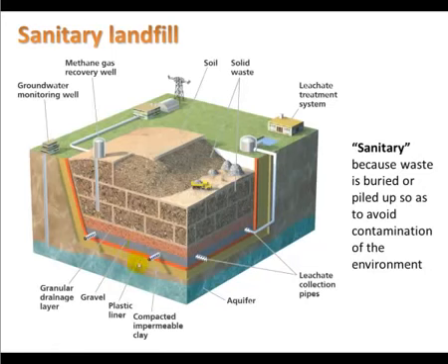Above the clay, we put some gravel, which allows water that might be in the solid waste to collect, and then we can pull off that water with pipes and analyze that water and especially treat it if it's seeming to contain some toxins. So above the water is where we have our solid waste, lots of it.